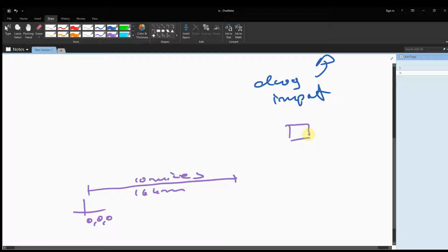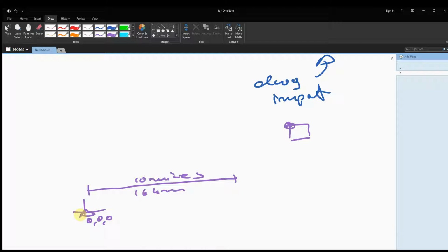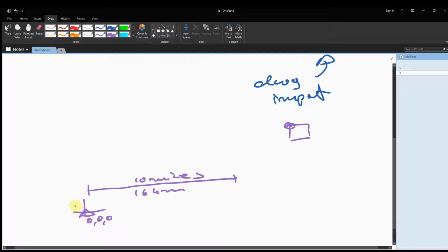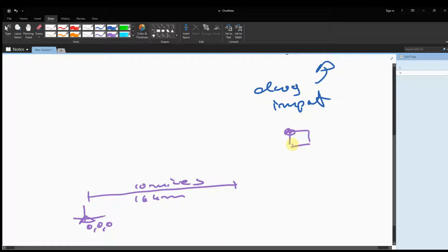Okay, so when we bring this in, this is actually not a big issue, because we could make use of this as our project base point. When our project base point is down there, it actually doesn't matter much, because it's about the geometry. If the survey point is down there, it doesn't actually matter. If the geometry is somewhere else, it doesn't matter, because if the project base point is basically down there, we can import it, for instance, center to center, and then everybody is happy, and theoretically the origin would then be here in the center of our geometry. Okay. So I have this further away.